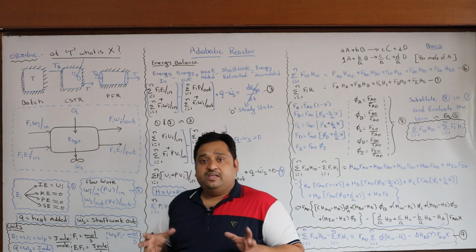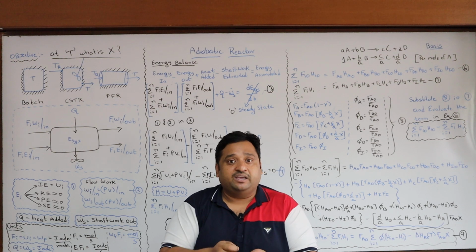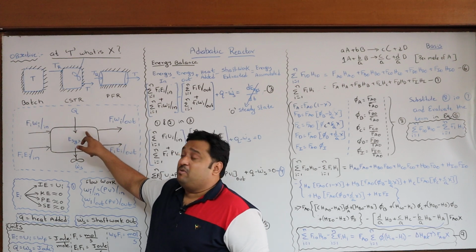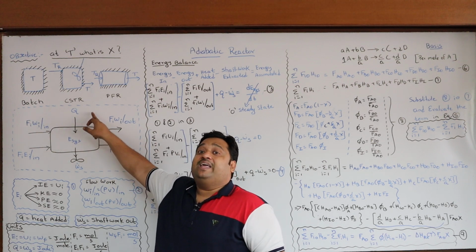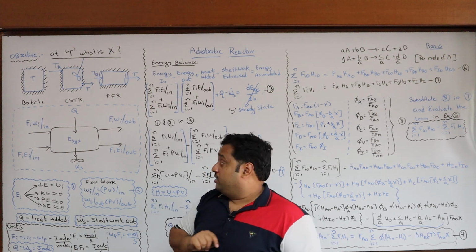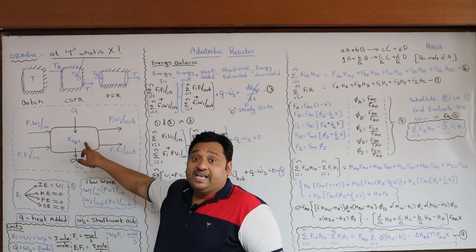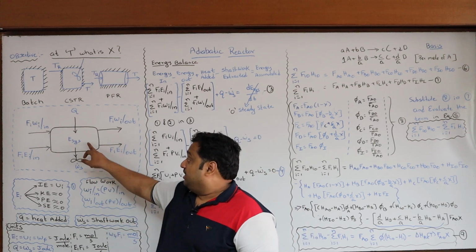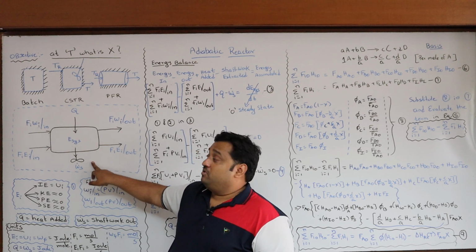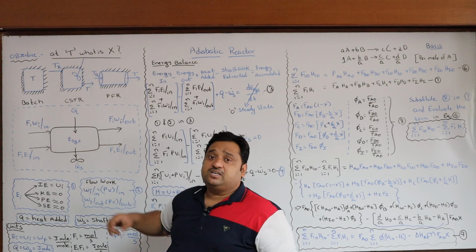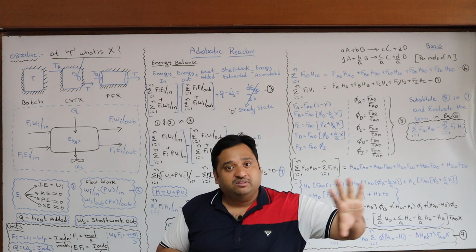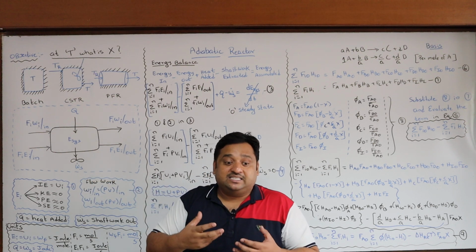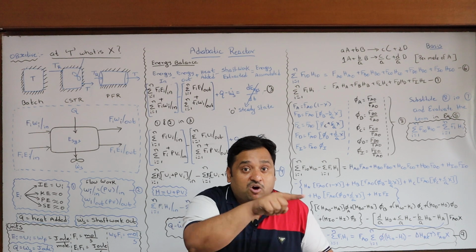And the other way, if I am adding heat energy, if I am burning, if I put some heat into the reactor, that means I am supplying some amount of energy to the system. This is called external energy, represented by Q. If the reactor is running a turbine or a shaft, anything from the reactor to the outside is negative. Do not worry. This Ws is called the shaft work done by the reactor on the surroundings. The arrow is in the downward direction, meaning the reactor is doing work on the surroundings.